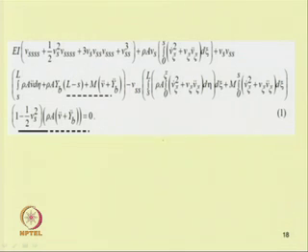So, where this subscript s represents ∂/∂s. One can note in case of the Euler beam equation, we have only the simple term EI ∂⁴v/∂s⁴ plus m v double dot equal to 0.